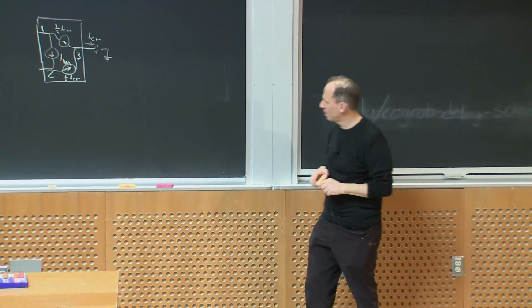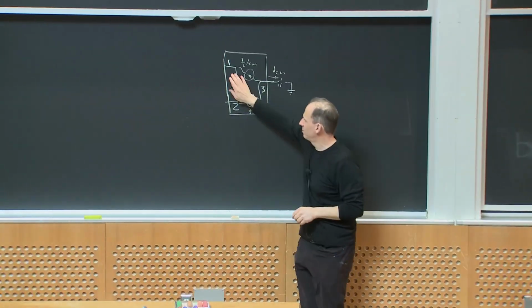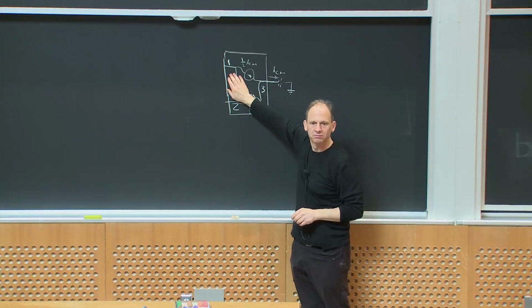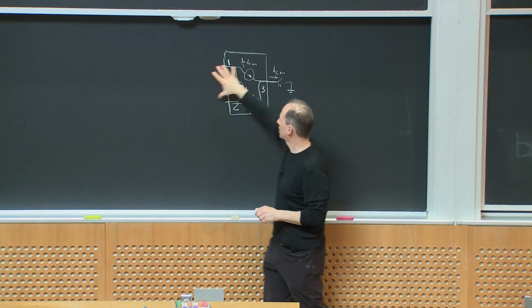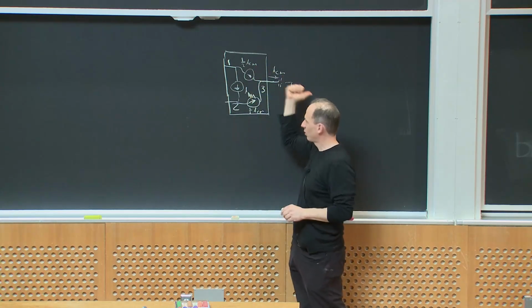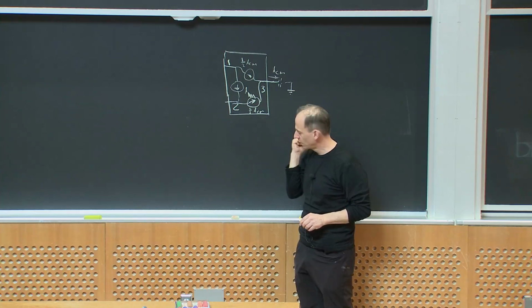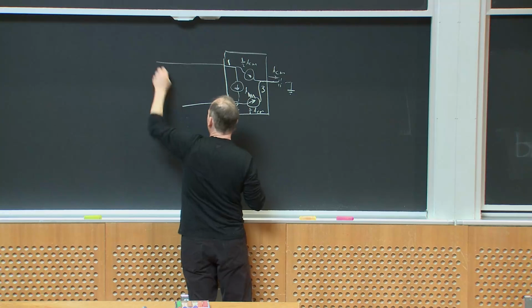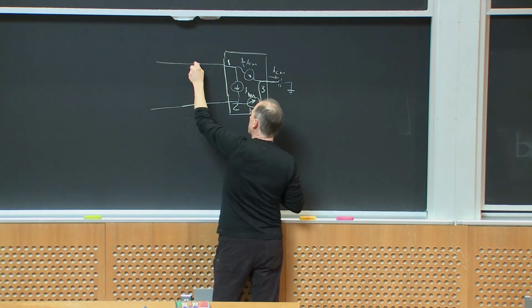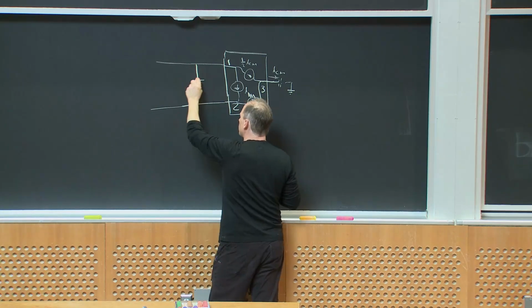So let me pretend for a moment IDM is 0. So let's just think. I have common mode currents that are being drawn together through pins 1 and 2 and going back through ground. All right? What would I do to filter it? Well, the first thing I usually put in my filter is a capacitor between the two leads, right?